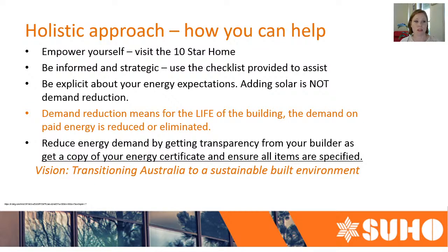So it's about making sure that you're getting what you're paying for, but getting what you are clearly, explicitly asking for. Don't focus on solar as demand reduction. It's not. It's band-aiding over the top. Solar is super important for housing, but the first thing that you should be looking at is this highly insulated envelope, the better performing passive building. It's the only way that we're going to drive down emissions on houses.